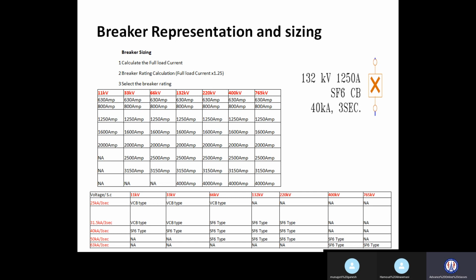And in the EHV system, meaning 66 kV to 765 kV, we use only one type of breaker, the SF6 circuit breaker. Understand, Ganesh, where we use ACB, where we use VCB, and where we use SF6 circuit breaker? Is there any doubt? Yes, sir. Can you explain why up to 33? I am explaining. Okay, now this is the classification.